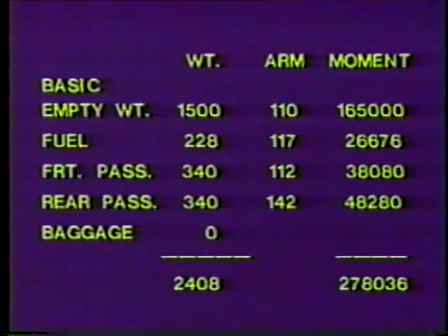Back to your worksheet, and let's once again use the formula weight times arm equals moment. It should now look like this. Now we have all the necessary information to determine the center of gravity location.